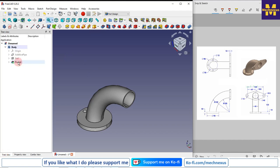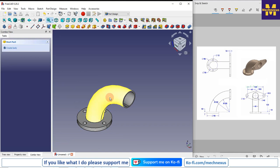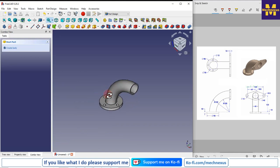Now I will select my pocket, and I will go with a polar pattern. From here I will select my reference, so I will select this axis, and the number of occurrences I will set to 4, and I will say OK. So you can see that we have made the 4 holes, and now we will make this flange.